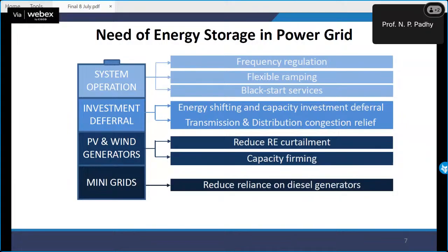The capacity of the line is 100 kVA. The line is fully loaded, and now you have a customer who is interested to draw another 5 kVA. So 100 kVA becomes 105 kVA. Now the distribution line or the underground cable needs to be reinforced, as we call it. So you put another underground cable next to that to cater to that customer. So instead of doing that, actually, locally we supply through a battery system.